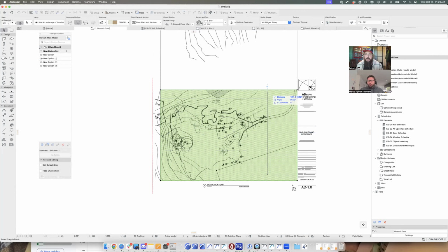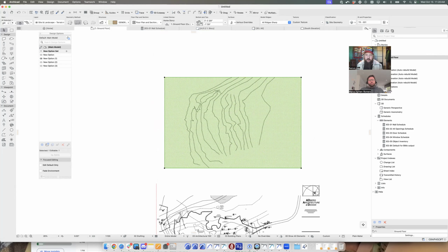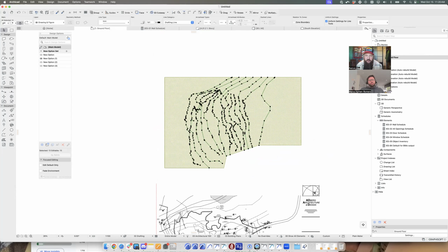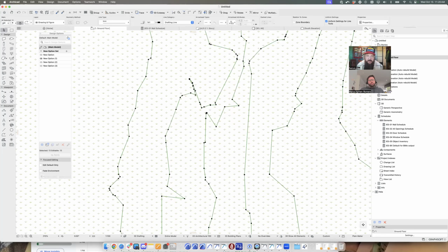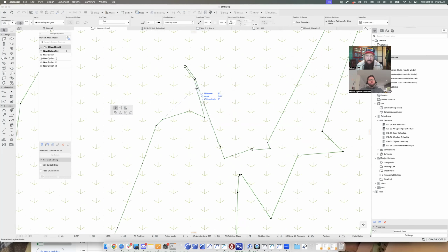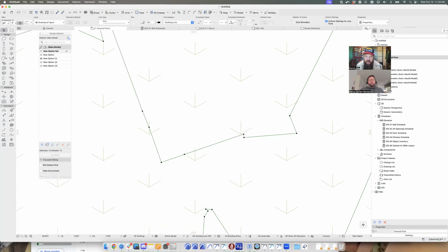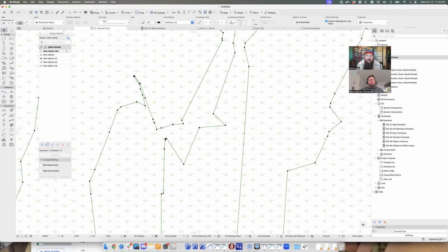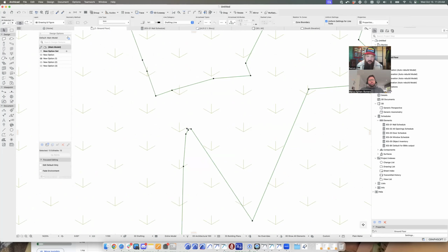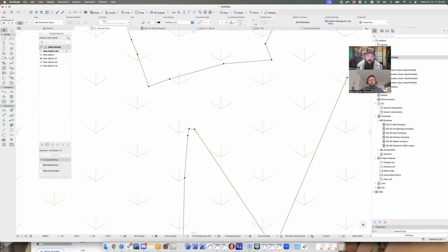So once you get it drawn to your property lines, we'll move it up here 200 feet so we're overlapping, right? So here this would be, I don't know, something like that. Get it close. Okay, so now I want to apply these contours to my mesh. If the contours are all usable and there's no nodes that are super close, there's no areas where they're overlapping, like this could potentially be a problem area right here. Probably not, as long as they're not overlapping and nodes aren't too tight together. You could do a little bit of preventative maintenance on that, checking where there are super close nodes. If we can clean some of that up, it's going to be better.